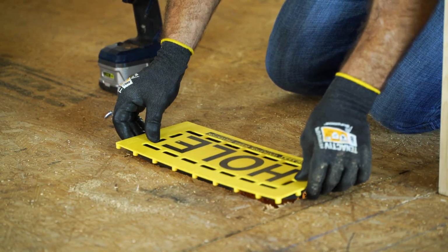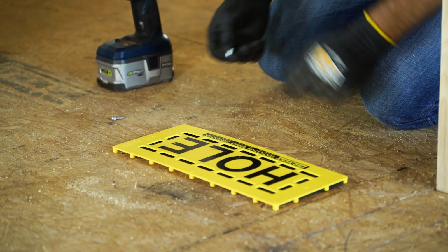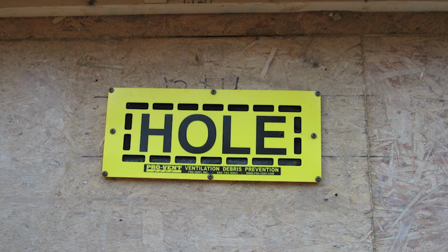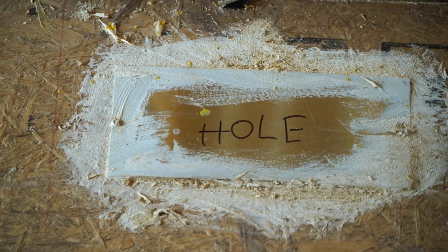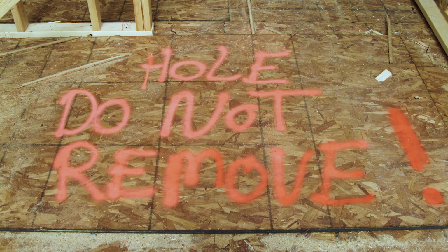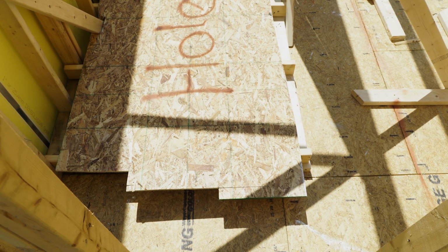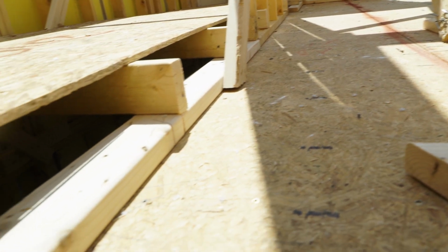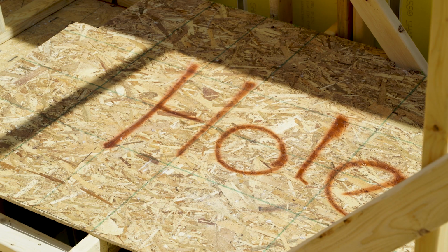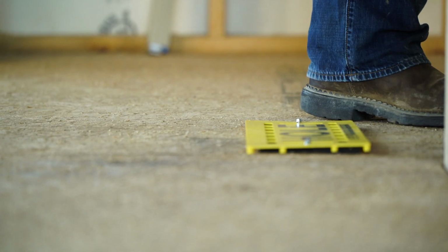Floor hole covers can offer the same protection while also protecting against falling objects. Any 2-inch or greater opening in the floor must be protected and covered. Floor hole covers prevent debris and materials from falling on other workers, but also serve to protect workers from trips and falls. Workers should only cover floor openings such as HVAC registers, plumbing floor cutouts, skylights, and basement stair openings, with a cover strong enough to support twice the anticipated load being placed on it.